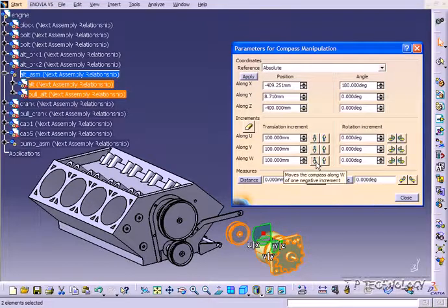So again, with this hierarchy system, you have to choose the highest part of your assembly or parts where you want to move. If I want to move the entire engine, I'd need to click there. If I want to just focus in on this little bit here, I'd click on the assembly there. With this, again, everything applies the same as the part. You're able to use the increments in here, or you can just click and drag, and you can use a face or an edge to translate and move your part along.